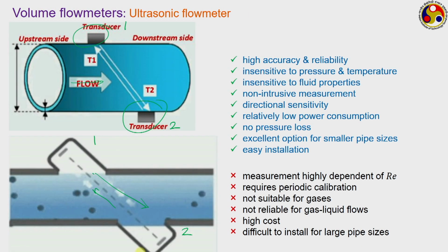So, this is the ultrasonic flow meter, which is again a quite common option. All these three that we have talked about, electromagnetic, turbine and ultrasonic based flow meters, are all very standard equipment, easily available from several vendors or manufacturers, and extensive databases are available about their performance characteristics. You can easily look on the internet and find a supplier to purchase any of these three kinds of meters of the desired specification. So, despite certain disadvantages for each, they are quite potent and common options for flow measurement.